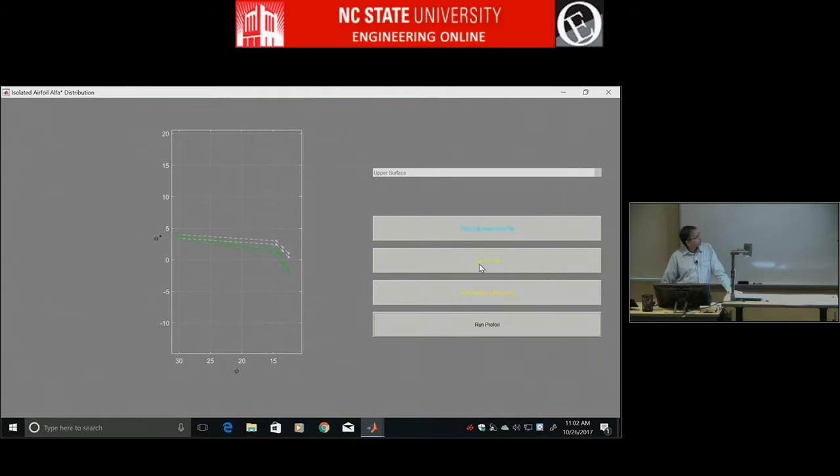Okay, let me do cursor edit. Click on cursor edit, and I'm going to draw something like really adverse. And you can say, wow, that looks really wrong. How can alpha star be -10? It kind of doesn't matter. You want a certain velocity gradient and you do what you want to achieve it. So let's say I keep it like this.